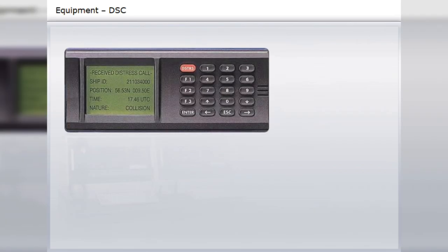Digital Selective Calling, DSC, is an automatic calling system for terrestrial radio communications. Ships can transmit distress alerts containing the most important fact about the distress, the identity of the ship and its position. This goes very quickly as the DSC is connected to the different nautical systems on the bridge, such as GPS. Subsequent communication will then follow on radio telephony.